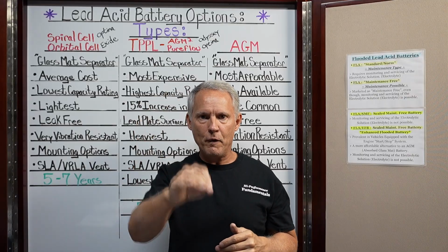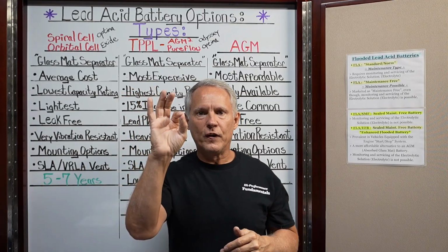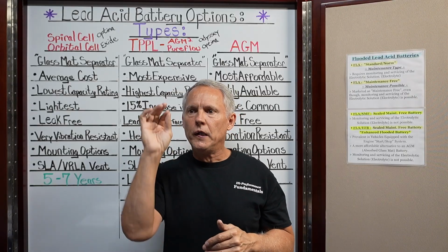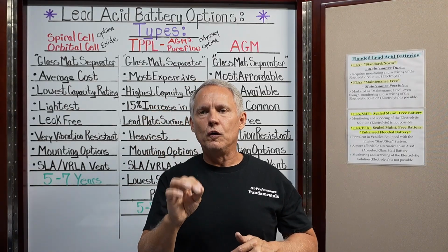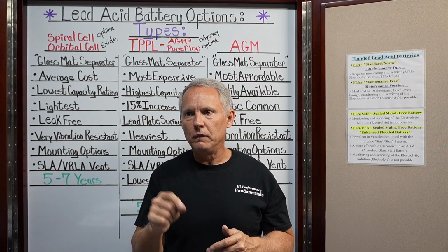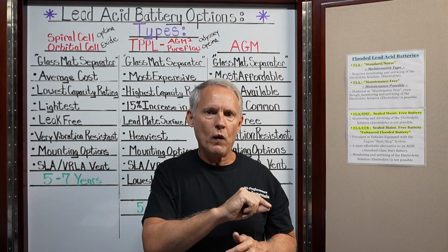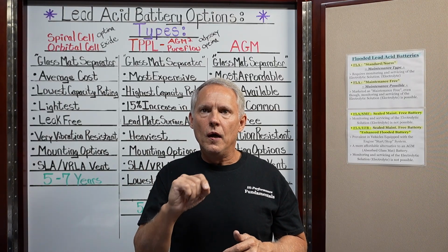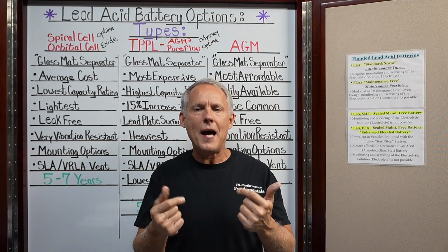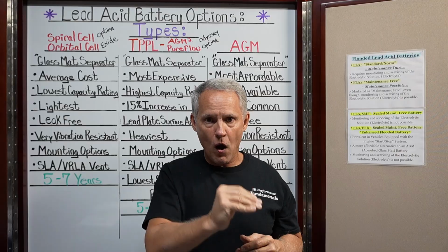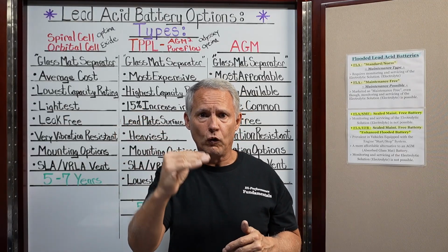So the efficiency of the battery goes down. The plate itself can overheat and start to actually flake away or erode, if you will. So if that battery undergoes overheating, overcharging, it can suffer consequences that you can't correct for. It doesn't become like you've ruined it automatically or it's completely dead, but its capacity may start to drop. Its longevity may start to drop.